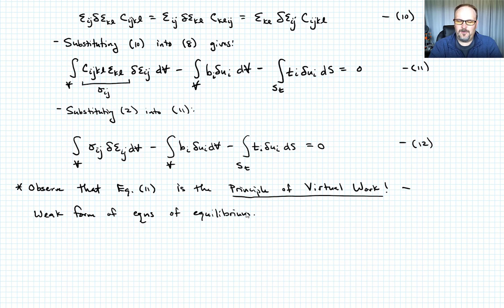In particular, we're going to focus next on the Rayleigh-Ritz solution, and then extend that to a finite element approximation. That's why we wanted to show this here, and hopefully you're now convinced that minimizing the functional, that is the potential energy, is what gives us the solution to an elastic problem.